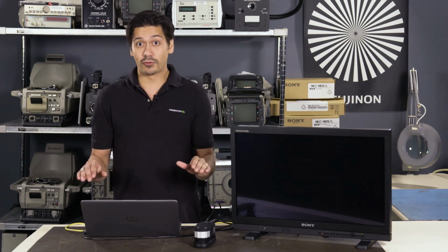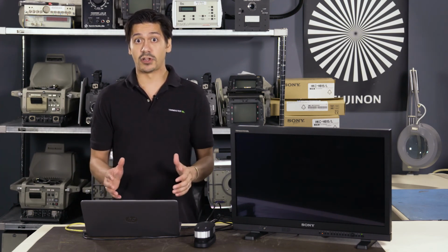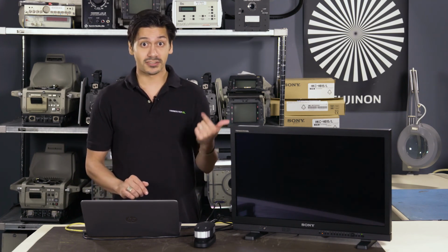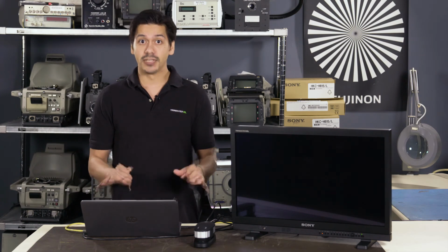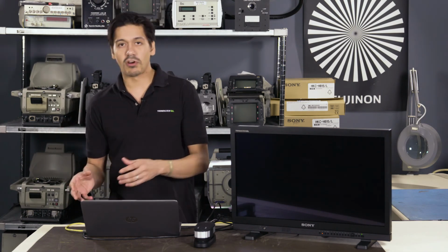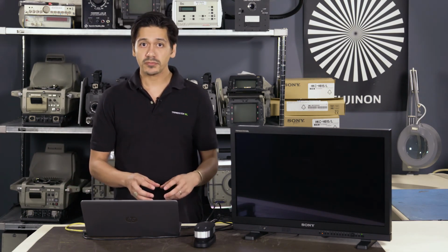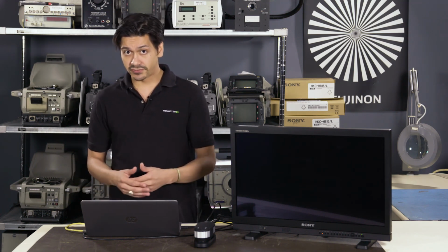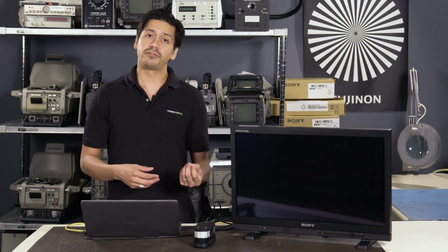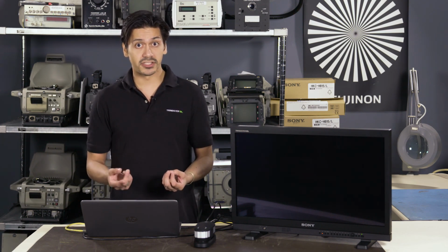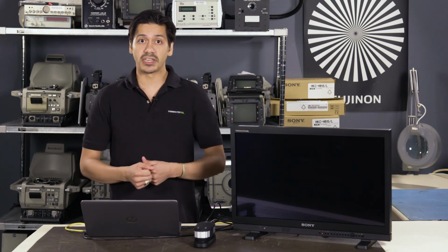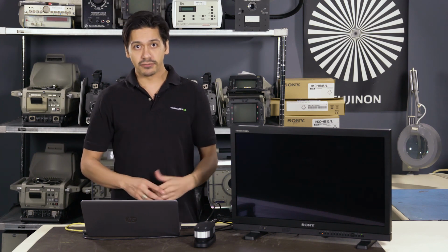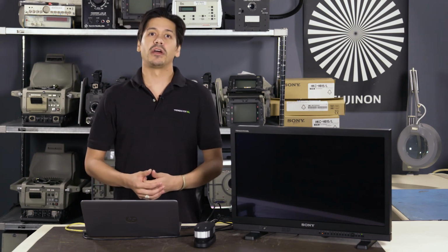The auto white balance software is a no-frills piece of software. It just wants to do a few things very well. Adjust your white balance and your luminance, and really that's it. You know, strict digital cinema work has different requirements versus broadcast. The suggested monitor settings for different gamma curves and color gamuts are specified in their documentation, and if you need more info on that, we did 2 videos prior in this series, part 1 and part 2, on gamma and gamut. So this is the auto white balance software by Sony for our PVM, LMD, and BVM line of monitors.